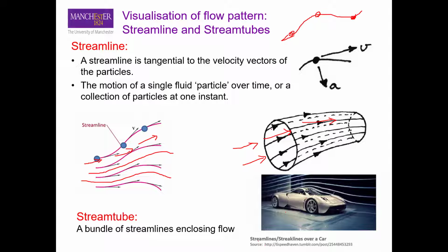It means that you have a slow moving fluid, and as the fluid is changing direction due to a restriction or a constriction, you have these streamlines coming together, and it shows that the velocity here is much larger. Let's say velocity vf, velocity vi. So this shows you that the final velocity is actually larger than the velocity in the beginning. Okay, so the distance between the two streamlines can tell you the value or the indication of velocity.